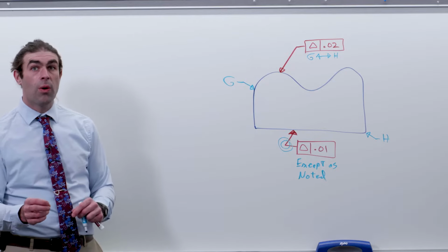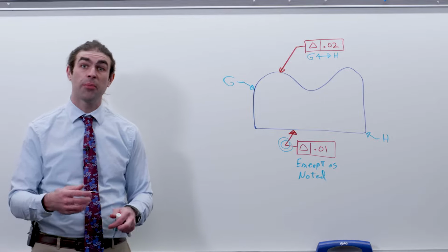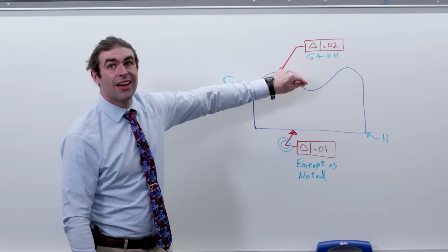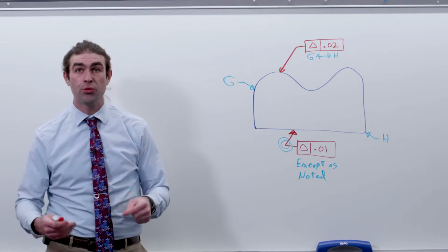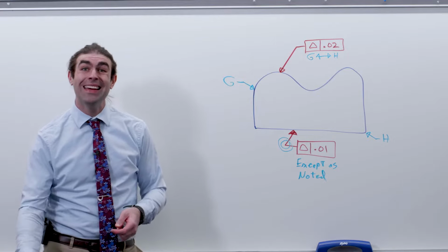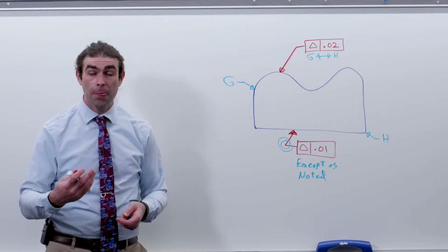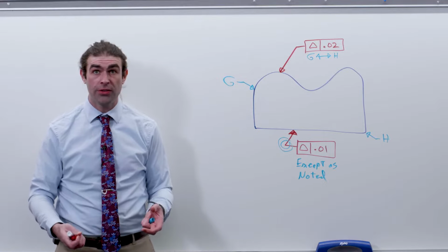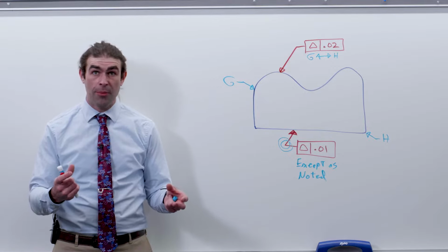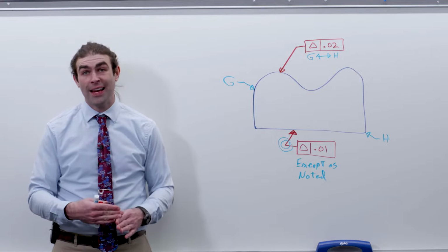The default requirement is a bilateral equal tolerance zone. Like I mentioned before, with this 20 thousandths, you get 10 thousandths on one side and 10 thousandths on the other of the true profile as defined by the basic dimensions. That's not always what the designer wants. Often you would have two mating parts where the basic size is 1 inch. Instead of changing the nominals to make them fit, you could just say, okay, I'm cool with the line-to-line fit.